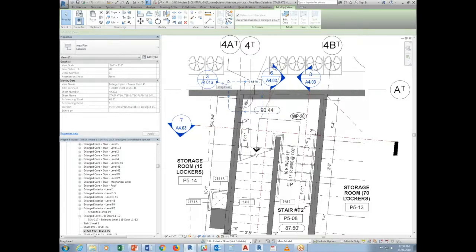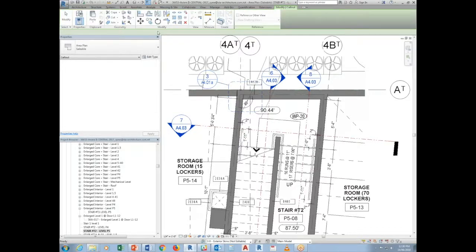But if you're doing a multi-story tower where the cores are the same, this is the method that I've used a lot. Basically, create one callout referencing this view, and then you copy it and paste it. So you don't have to redo all that tagging, because every time you do this callout tagging, referencing the view, it's a lot of clicks. Whereas if you copy that and paste, much faster. It's usually hard to find the related view in that list.